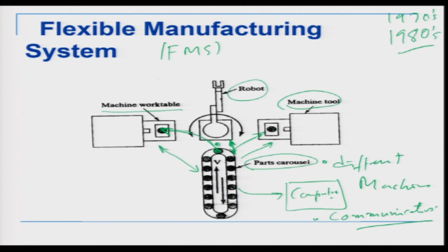Now if you watch here, something very interesting is that there is one part here, and there is another part here. Now if the robot picks up a third part, what will happen is it will get what is called deadlocked. There is a term called deadlock. Why? Because a part is here, a part is here. Now the robot has picked up one more part and it can't keep it here, nor can it keep it there, nor can it take out the parts from here.